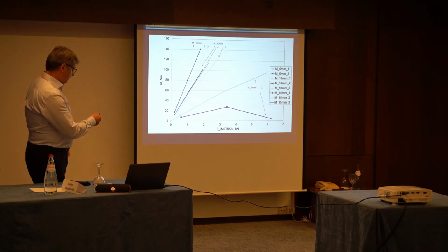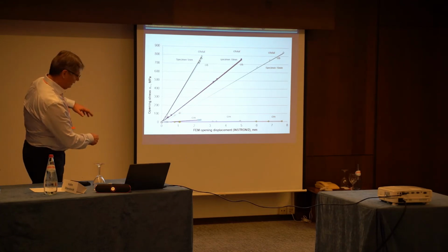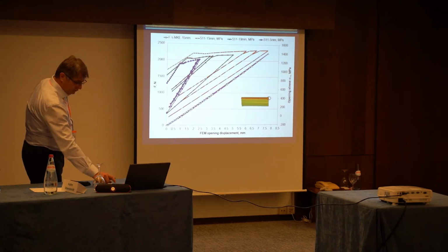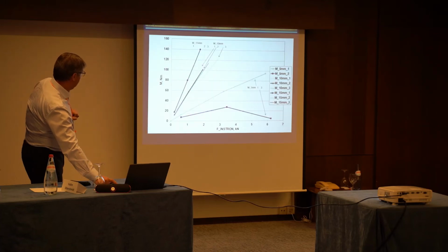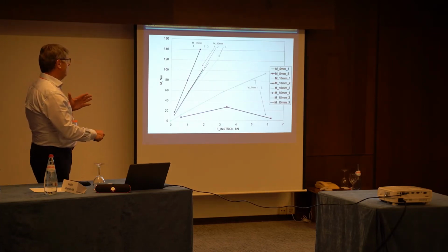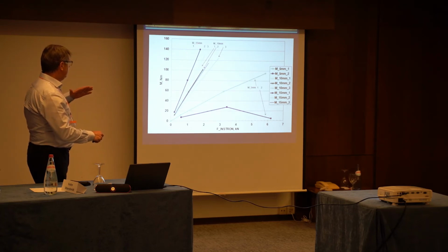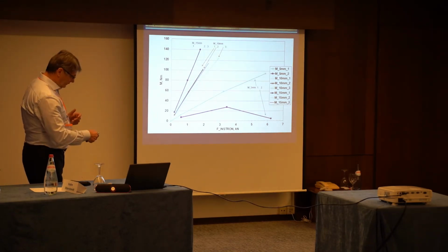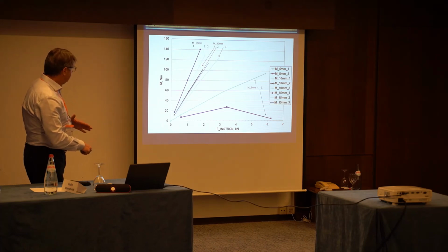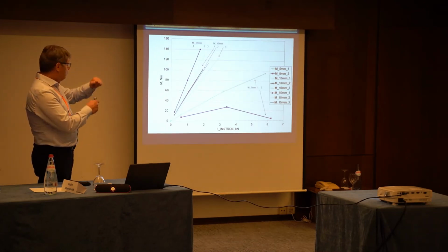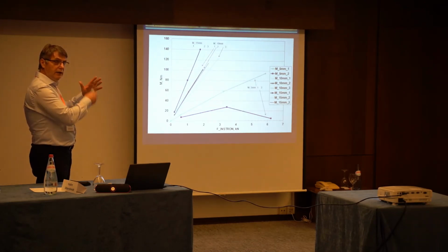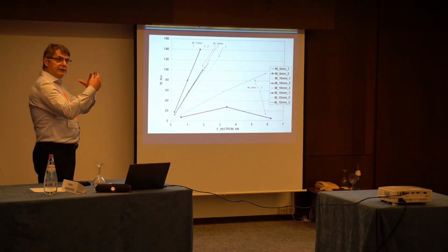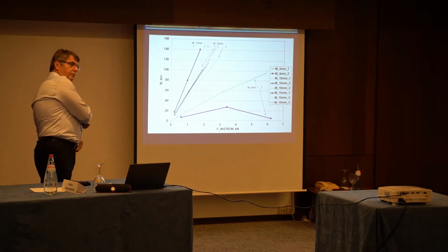Here we calculate this stress which we have from the force. Then we have the bending stress, so we calculate for the moment. You have here the moment for 15, first loading, then this is from instrument data, displacement and load. You have the second, you have the third for 15 millimeters, and you can see that each cycle which you repeat has a different behavior, a different slope, because you already have some plastification, and of course you cannot come to the same point as before.